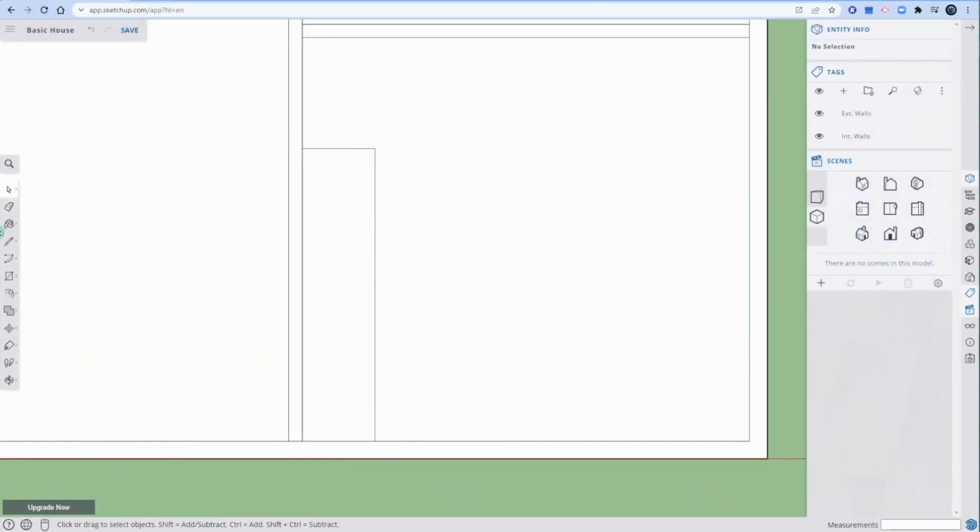So I'm going to first draw this 4.5 inch wall all the way around. I'm going to go here on edge, 4.5, enter, endpoint, go over. I'll go from this side this time, go over. Oh, look, it's starting to recognize that we like the 4.5, and it says 4.5, so I'm just going to click. And then go up, edge, spacebar to get out. And then I actually don't need that little nook, and I don't need that little nook, right? These are all interior walls. It's the same wall. I can even get rid of that one, the points along it. I do want to keep these exterior ones here. You'll see why later, but there we go.